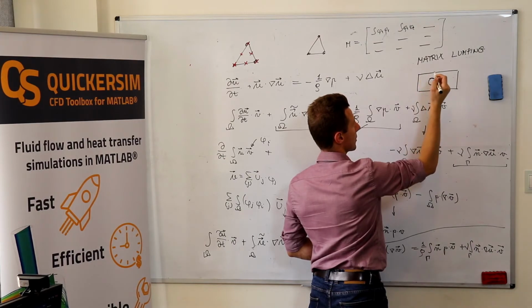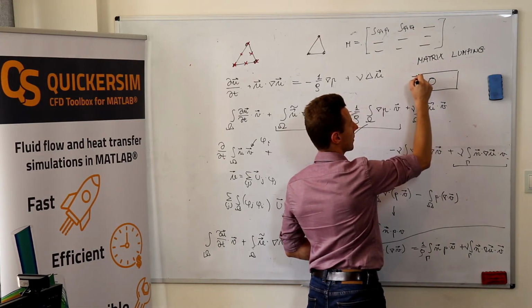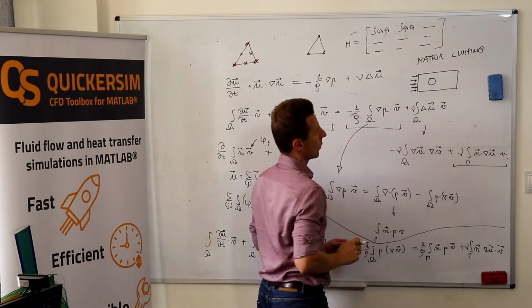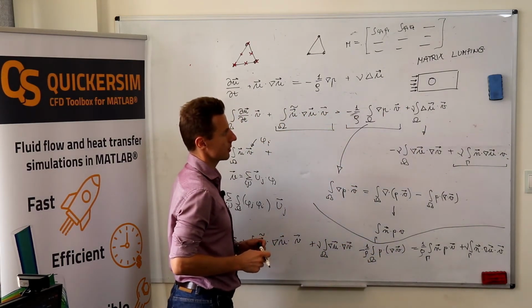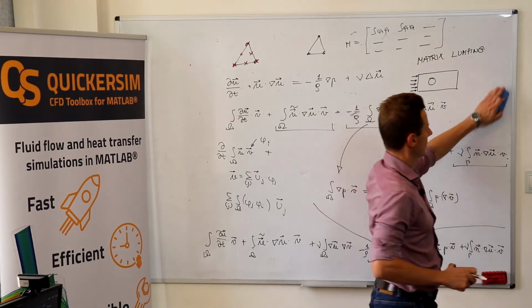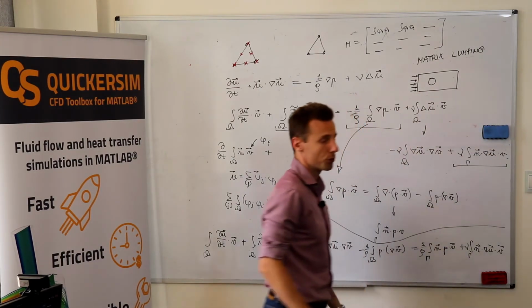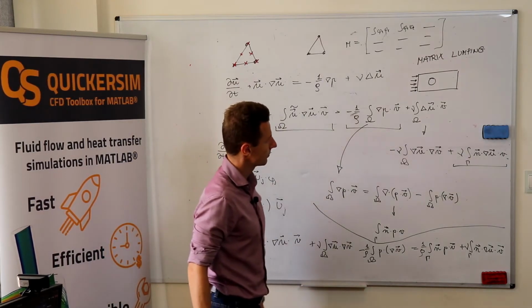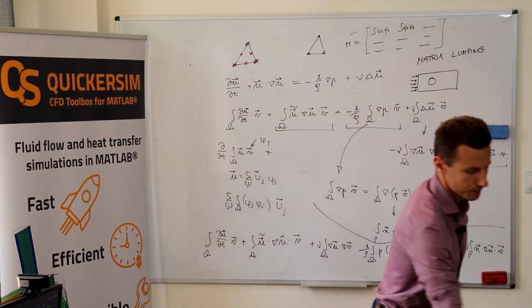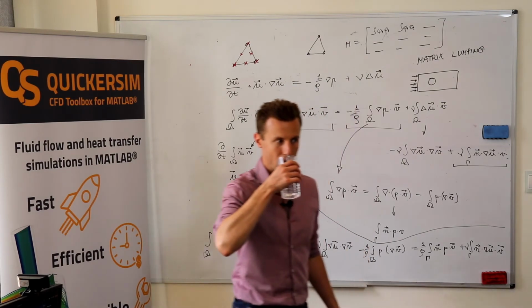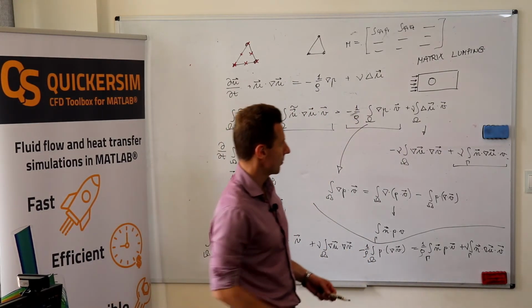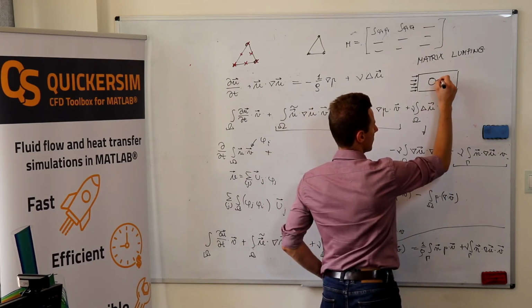If you want to solve such an incompressible flow problem, what kind of boundary conditions would you want to impose? So the zero velocity, no slip, on the cylinder, and the bottom and top wall. Exactly.